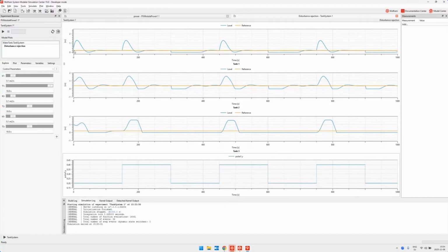And then we have the actual level in blue, and how the controllers manage. They're not very good, right? There's a lot of overshoot, and then after 150 seconds, it seems that they reach the desired level. And then as I'm feeding it a pulse of rain coming into the top level tank, once this comes, it overshoots, and that's how it continues.